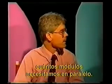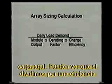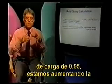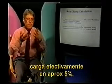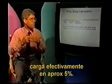So what this leads us to is our final equation for calculating the number of modules that we need in parallel. We have our daily load demand. That's what we need to supply every day. We divide that by the charge efficiency. You can now see that if we're dividing by our charge efficiency of about 0.95, we're effectively increasing our load by about 5 or so percent. That's taking into account that battery inefficiency.